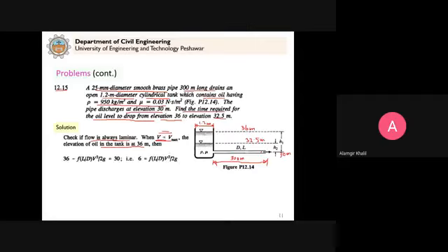So now we consider this equation. This is Z, 36 meter, minus the major head loss, equal to this 30 meter here. We ignore other terms, clear? Because we have oil flowing and consider laminar flow, other than this major head loss, because the length of the pipe is 300 meter, which is significant, we ignore other terms.